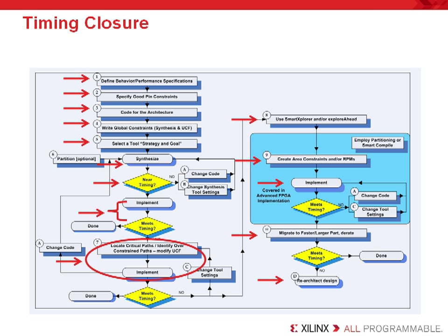If that's the case, you're going to have to re-architect, re-synthesize for a different device, etc. And this might mean inserting additional pipeline stages or getting another designer to evaluate your HDL code. But the key is you have to find out why you have too many levels of logic in your timing critical path. So as you can see, this is rather methodical and challenging, but the key is that the sooner you evaluate your HDL code and optimize your design to use the FPGA's dedicated hardware resources, the sooner you're going to meet your timing.